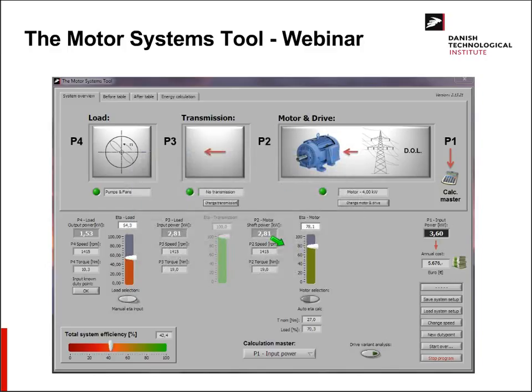So that means that now we see a change over here, and we now have the entire chain of the entire motor system telling us the efficiencies of all the components included. Of real-life measurements, we only had the electrical power input, and then we had the hydraulic output in terms of pressure drop and flow on the fan. And then we have all this information.